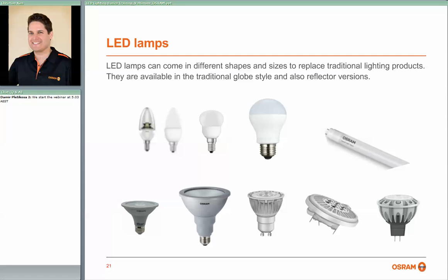The last thing that I guess is a con here would be due to international standards for certain lamp types. There's sizing and weight restrictions as well. So that can restrict, in essence, the light output of some lamps, because you can only fit so much heatsink in there, for example, to draw away the heat.